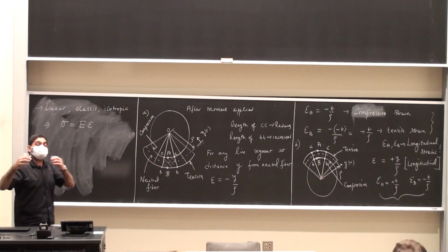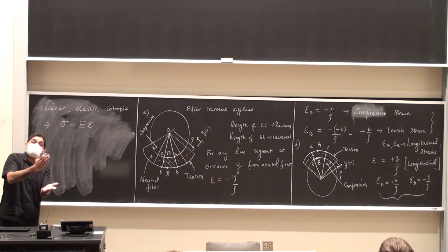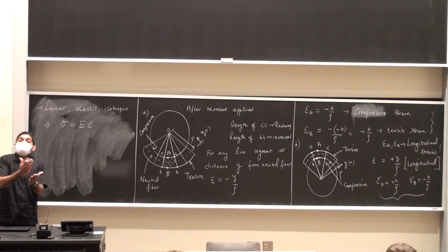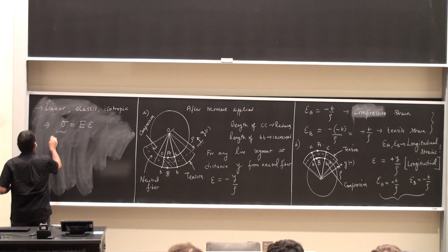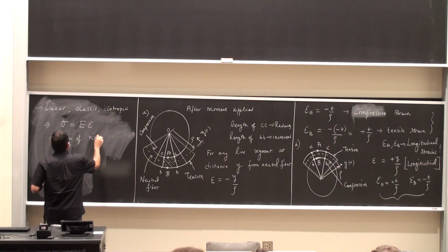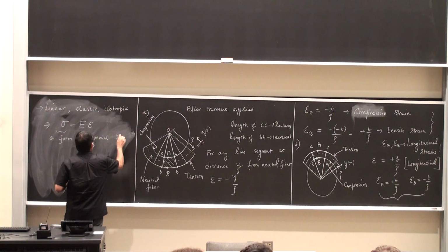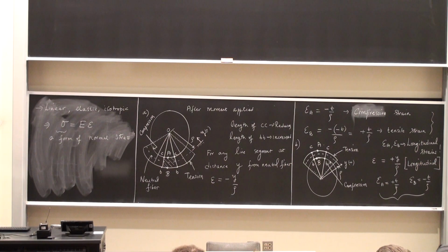So the bending stress is also a form of the normal stress, which means in a problem that has both axial loading and bending acting, they will be additive. I can either add or subtract the bending stresses with the normal stresses. So this is also longitudinal. This is a form of the normal stress in bending, but it's caused due to bending.